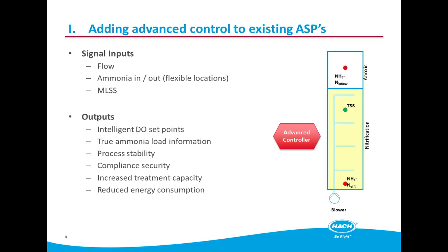What we also have, which we've not covered in this presentation, is a sludge age controller. If you want to alter the rate, or optimize the nitrification rate, then we would recommend a sludge age controller. It's not really got the attention I think it deserves in the UK, because historically we generally look at a fixed mixed liquor level and fix that.